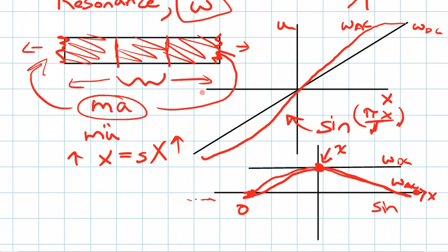And this mass times acceleration is actually what causes the main resultant of the forces in this vibrating structure. Because there's nothing on this side to tug at it, there's actually no stress at the boundary. So this is one of the boundary conditions.